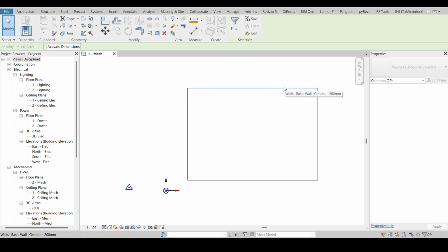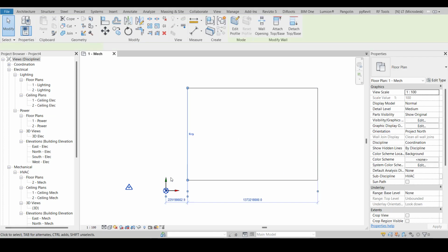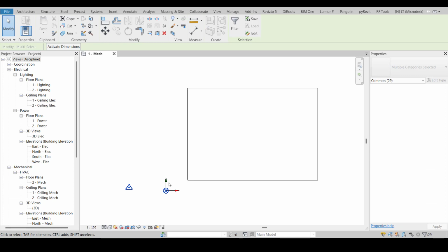So like that we can count. Similar way, this is to count the project thing. Now this we can keep 0 0, and it will still work for our project. There is no problem in getting the coordinate for our project, but we have to fix this point as 0 0, and we have to mark this point physically on our site also.